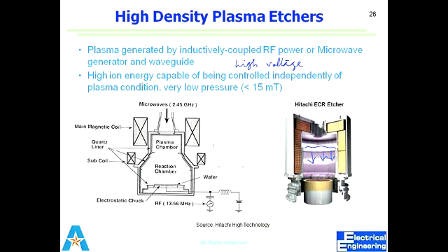So when etch rate is high, you lose the control. In this case, because it's high, very energetic ions, so high energy of the ions, they actually damage your surface as well, the mask or the substrate. So if you want a very high etch rate, and it's okay for you if the surface is damaged, you will go with high density plasma.